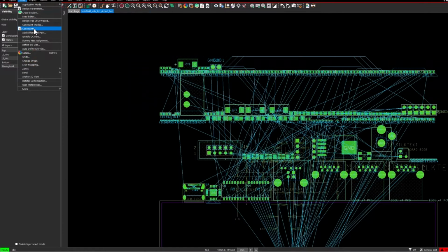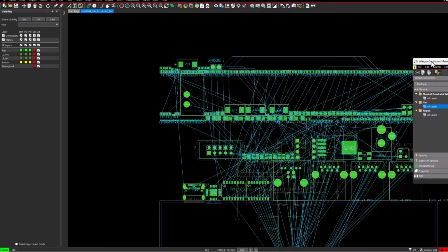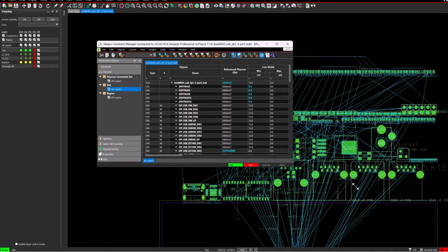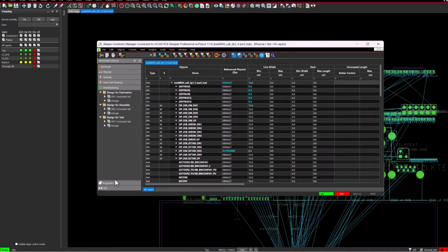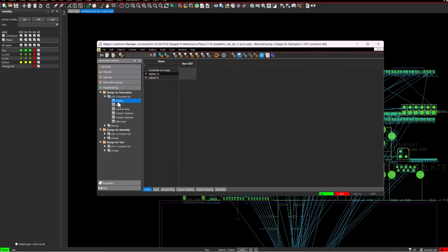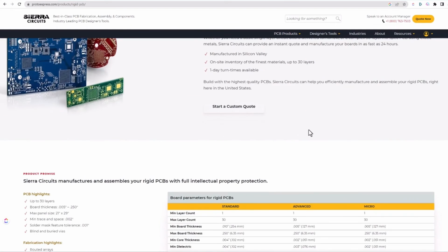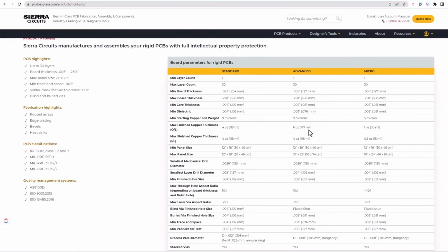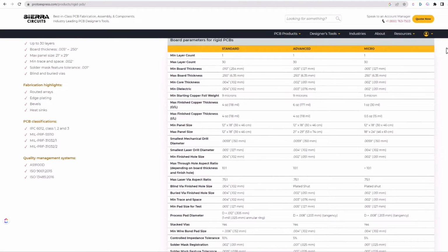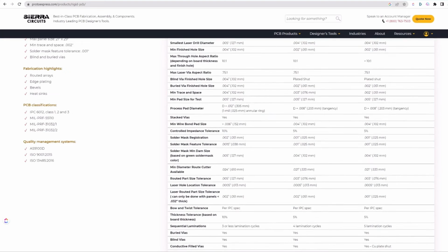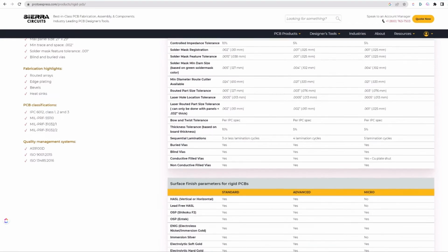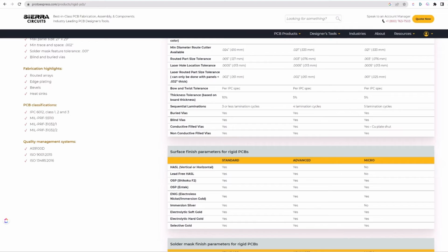Okay, now that the stack up and impedance calculations are all finished, you want to do your constraints. There's a whole heap of constraints that need to be taken into consideration for design for manufacturing, design for assembly, design for fabrication. You need your design for fabrication constraints that you would get from your manufacturer to see what minimum trace widths you can work with. In fact, you should be looking at this before you even set your impedance and trace widths, because that affects what the manufacturer can do as well.